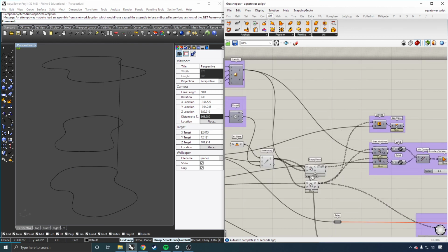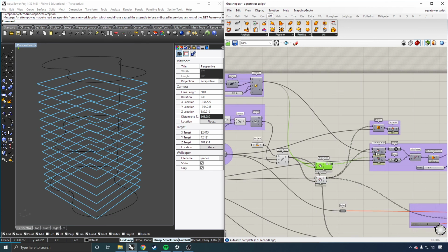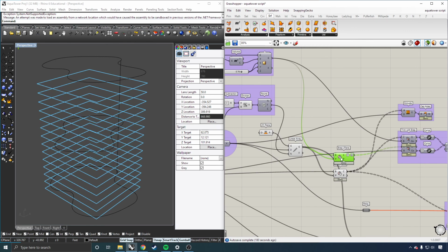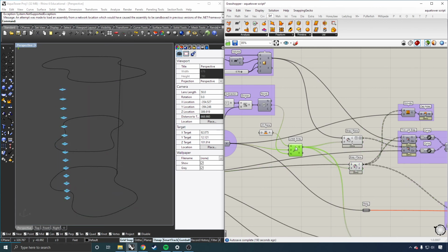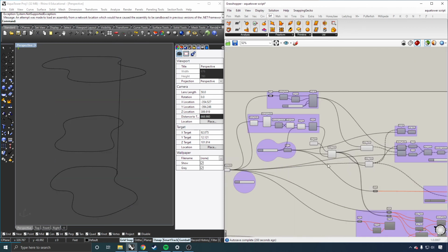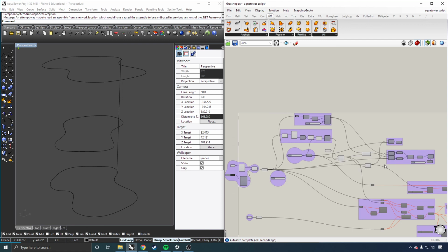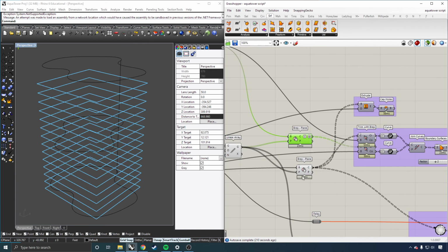So we've got both of those. And then we do have our cuts of these shapes. This one you'll see is coming from the bounding box. This is the BREP. So the geometry is a BREP. Boundary representation is what that means. We'll talk about that a little bit more later too. And then in this case, the BREP comes all the way from the surface. Just like we'd organize here, where this is kind of below this one, this shape is below this one. So we've got our lines, and we've got our shapes.